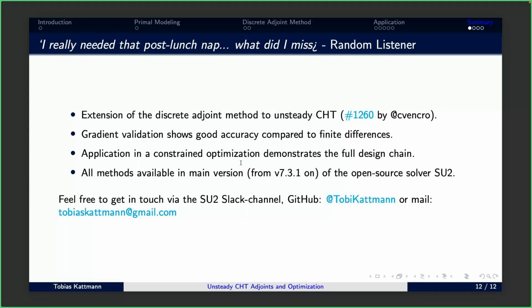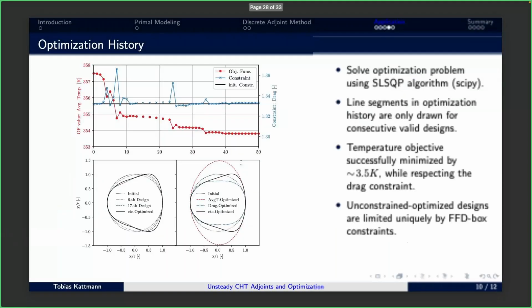But I've also converged the primal and adjoint quite a lot. But especially when going to single zone fluids, in this case, we're talking about, I don't know, a couple of minutes. If you couple it, it already grows. And if you compute an adjoint for that, I think for me, the factor was something like 3 or 4 that the cost grew. But it was also because I was very conservative with linear solver options, iterations I gave it to really be able to show an optimization that comes to kind of an end.